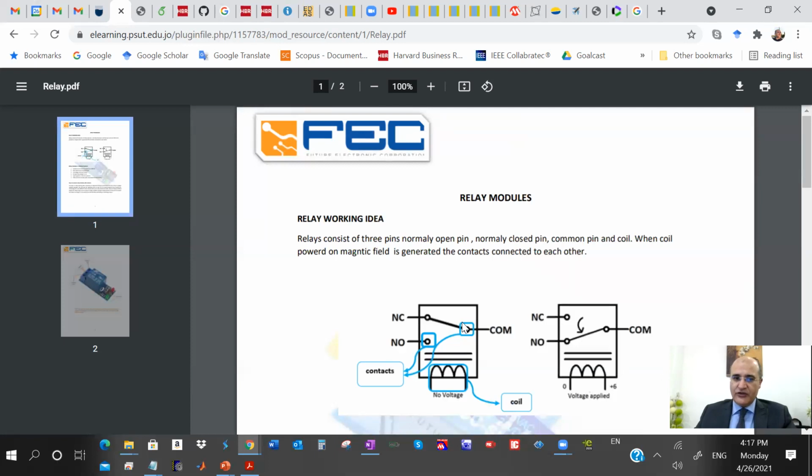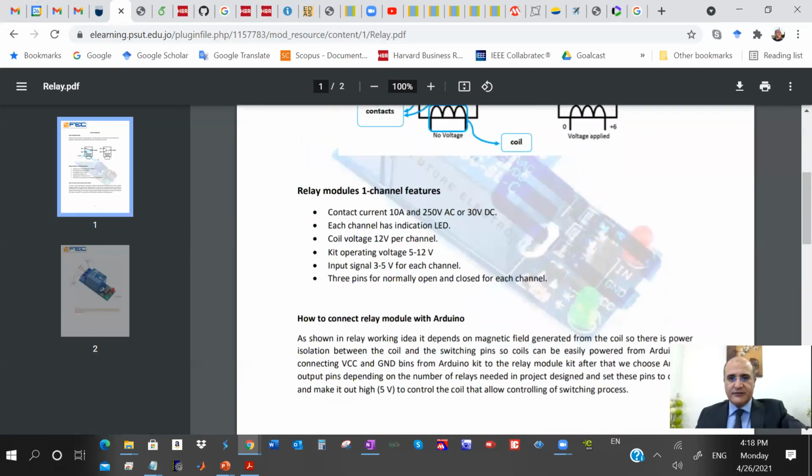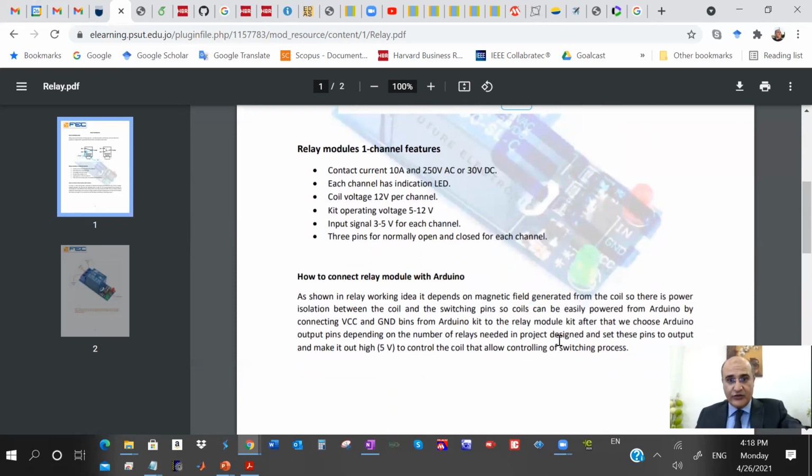Usually the circuit is closed. If you want to open it, yani disconnect, you write a 1. What if it is the other way around, normally open, where the circuit is disconnected? If you want to close it and turn on the appliance, you write a 1. It's up to you to use normally closed or normally open based on what you want to do. And these are the voltage applied to the other device, the device you want to control.